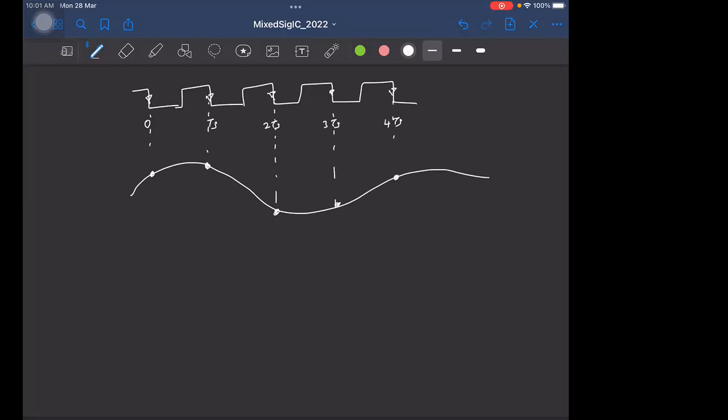Okay, and this was achieved in an interleaved fashion by having two ADCs, right? The first ADC was sampling at, say, these points, 0, 2TS, and 4TS. And the other ADC was sampling at these points. I'll mark them with a cross: TS, 3TS, and so on. And you switch between the two ADC outputs to realize the full rate ADC, right?